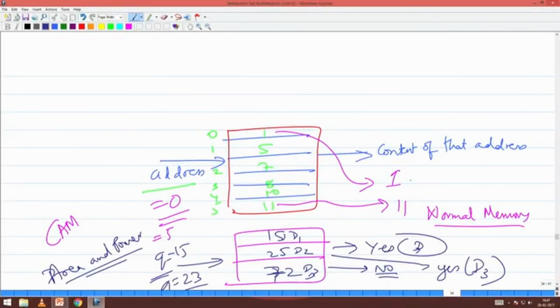So what was my crib about content addressable memory in contrast to normal memory? The content addressable memory takes a lot of area, time and power. Now if I am going to have 1 giga of content addressable memory, that is all, the chip will be content addressable memory, not CPU, okay. You will spend more time on that.